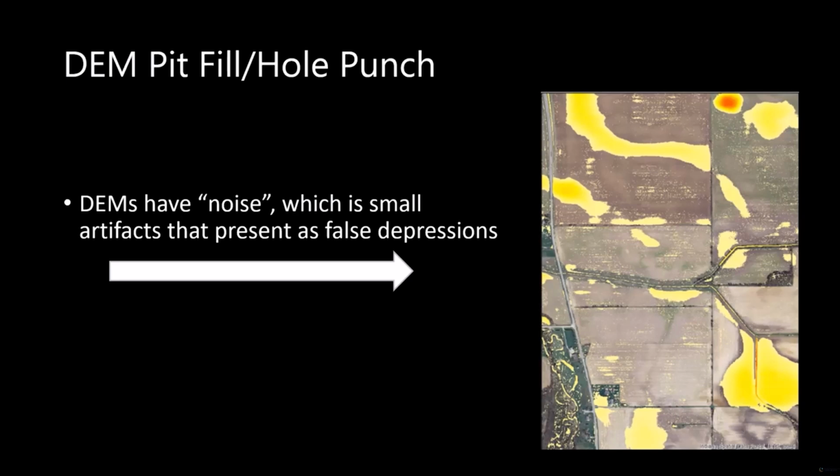The inputs are relatively simple. We need our DEM, and then we need to specify our maximum filled depth, which will be measured with the same vertical units as our DEM.